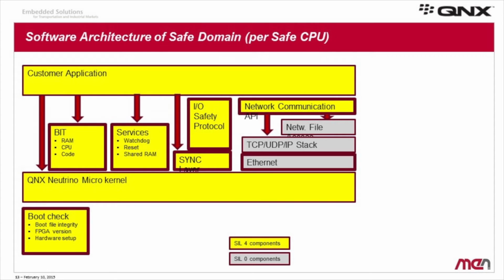To have a safe system, you also have to deal with built-in self-tests, for example. You have to show that the memory is still working all the time. So you have to do some tests and measurements all the time. You also have to ensure that you're booting the right operating system, that you have the right configuration of your system. So you have to do all these things on system boot.